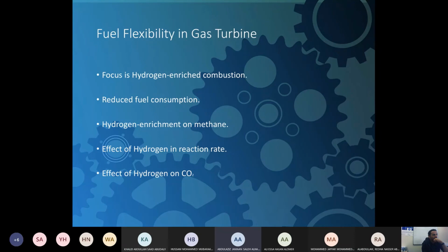Also, inclusion of H2 in the mixture of CO2-diluted oxy-methane flames shifts both the static stability limits, blowout and flashback, to the leaner side with increasing hydrogen fraction, as hydrogen improves the chemical kinetics of oxy-methane flames.